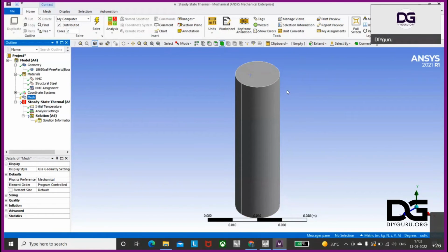Okay. So for example, if at this edge, at this point, I apply a force over here. Okay. So you can understand when you apply force over here, some deformation will act at this point. Not the whole thing will disturb. Okay. So for this software to understand, you have to divide this whole geometry into very small elements.